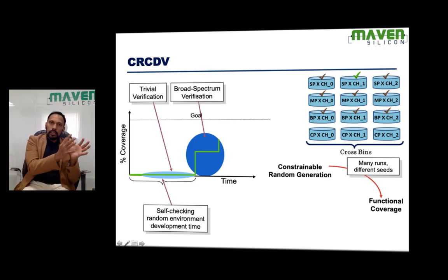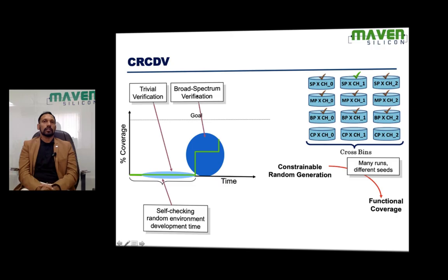We implemented the verification environment based on the architecture and verified it with the help of one small packet. Now the environment is stable. It works beautifully. Once we gain the confidence that the environment works fine, there are no issues and all the connections are proper, we can think of generating hundreds of packets. That's called broad spectrum verification.